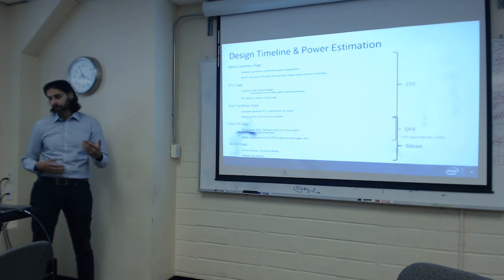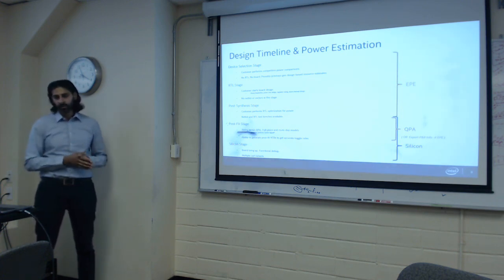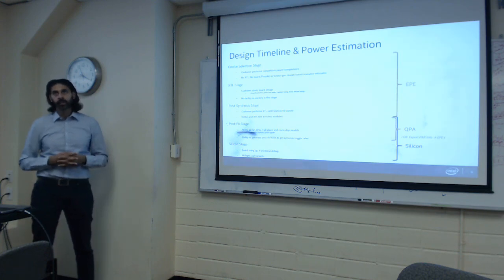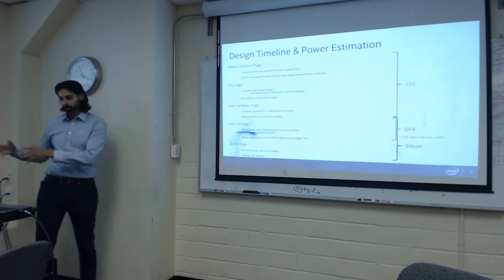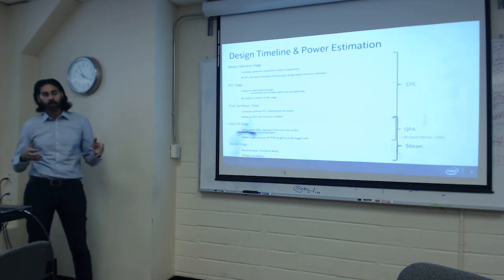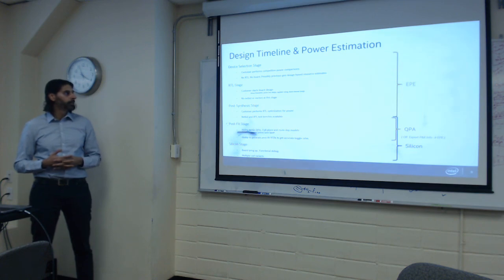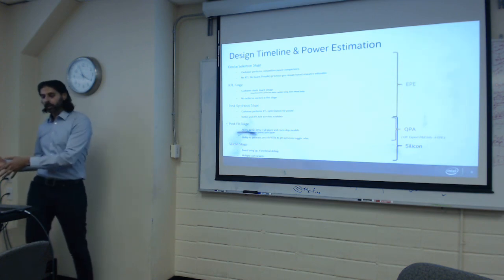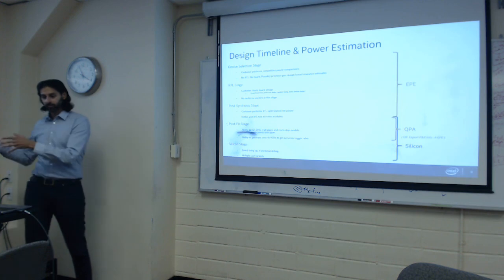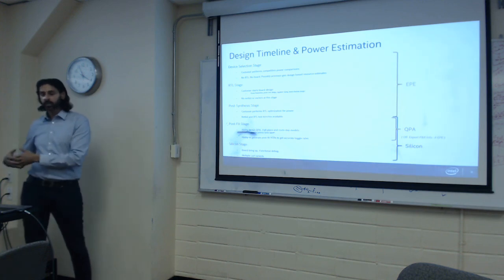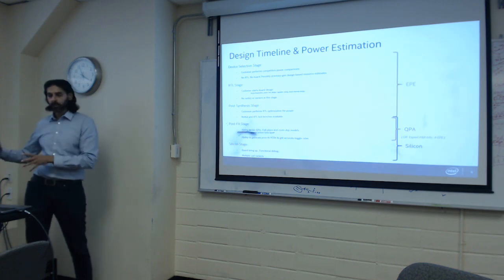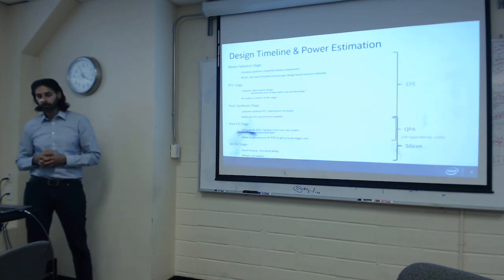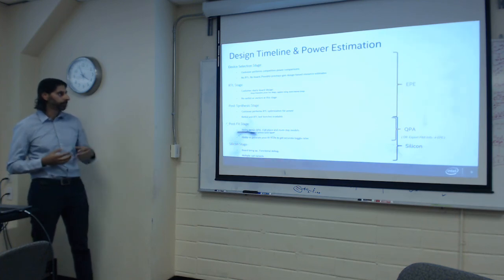And then RTL. So then they start actually coding up RTL. But oftentimes with modern FPGAs, it's not just one FPGA customer building the entire system. There's someone writing RTL, there's someone designing the actual PCB, and they're often working in parallel. And so in this stage, the PCB designer, even though the RTL is not finished, needs to start building up the PCB, and so they use the early power estimator to get early estimates and figure out the scope of what they need to design for on the PCB side. And so again, they use EPE for that.